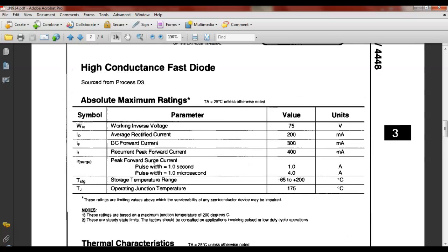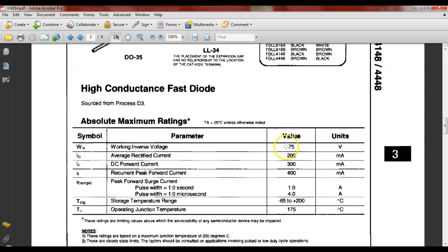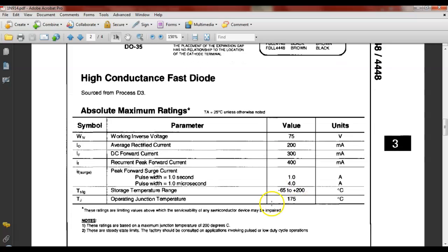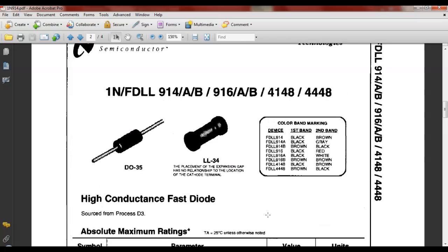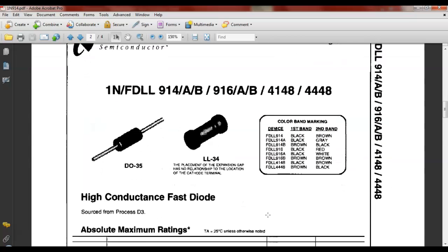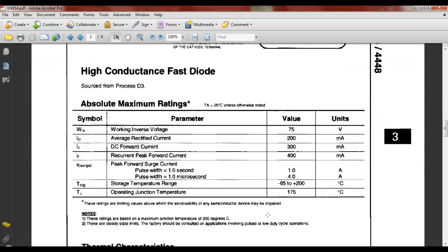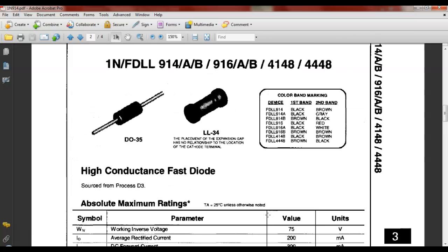So that means when we get around 75 volts, we should see this breakover. Now the problem is that if we let this thing break over and we don't protect it, then this is going to cause problems. But we're going to protect this with a 1 mega ohm resistor, which some of y'all hadn't even seen before. What's the color code for 1 mega ohm?